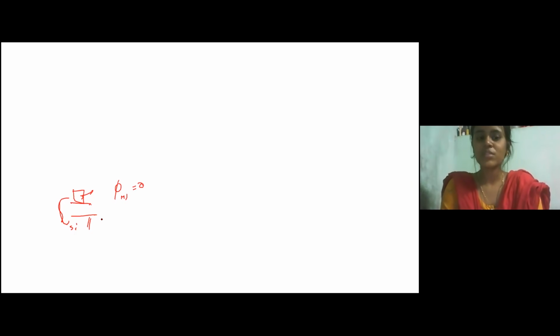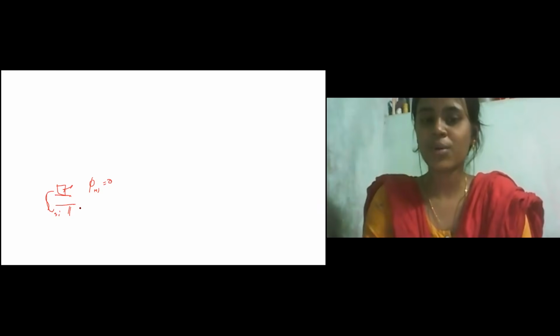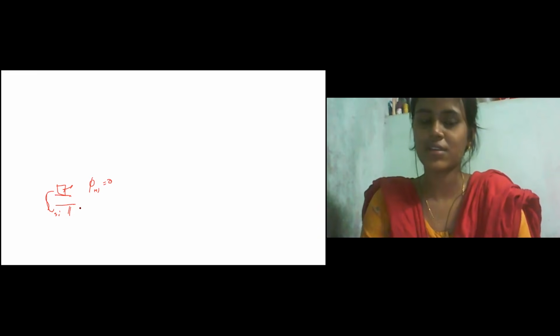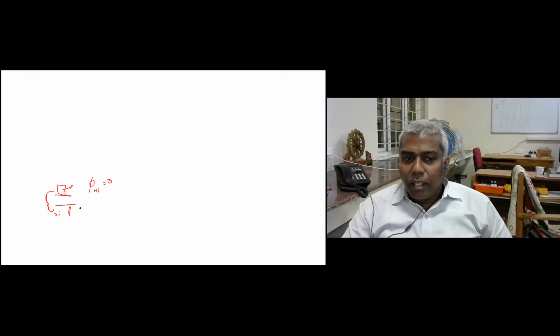Is it possible to change the threshold voltage value, sir, by means of doping or any other way, in order to get the depletion region? Of course. For example, this depletion layer depends on the silicon, which is doped p-type. So depending on the concentration of the silicon, and also the material you're using, you can use zirconium oxide or hafnium oxide.